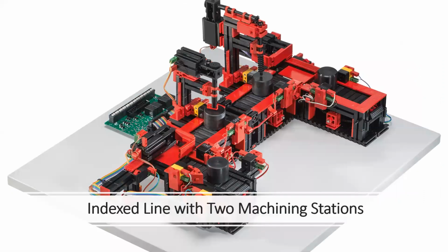The next model is the indexed line with 2 machining stations. This model features a U-shaped conveyor line consisting of a milling and a drilling station and 4 conveyor belt sections. Components on this model include the 4 conveyor belts, as I just mentioned, 8 XS motors, 4 push-button limit switches, 5 phototransistors, and 5 LED light barriers.